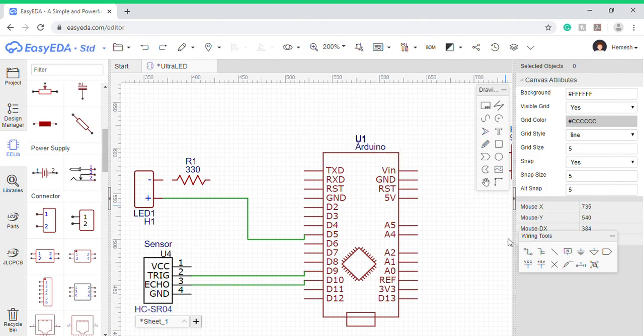So we'll connect the resistor in the same way. We need to right click on the header and then right click on the resistor. They're connected now. Now sometimes the resistor's negative is very far from the Arduino Nano's board. As you can see, this is not easily connectable as I need a very large wire to do that. So what I can do is directly use this pin, which is the net flag VCC. If I click on the net flag VCC, something like this appears. I just need to connect it to the VCC pin, and now they're connected as you can see.